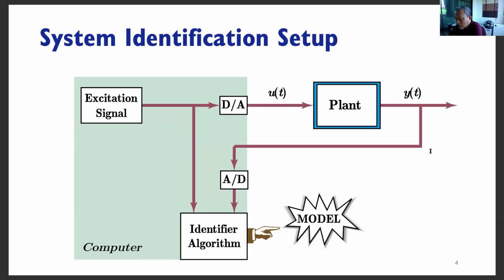That is important. You can design the hardware to produce the excitation signals, or you can simply do the programming, simulate it, and inject it to the plant. The important thing when you do data collection is that the sampling must be right. The process must be ongoing and must not disturb the plant while the plant is running.